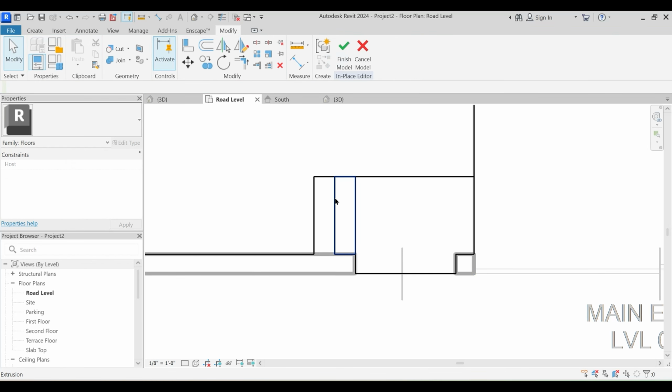Okay, now let's get rid of this particular section for now. Okay, so the next step is now we have to start building up the structure, the superstructure. Okay, so what I'll do is that I'll just go to wall and edit type and duplicate this and call it main wall 9-inch. Okay, and edit, and herein material, I guess that already that material has been defined. It's just a simple paint. Okay, wall paint, fine. So just click OK and apply and OK, and we will move step by step.